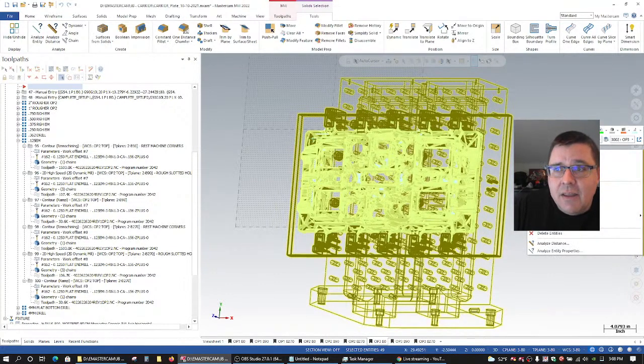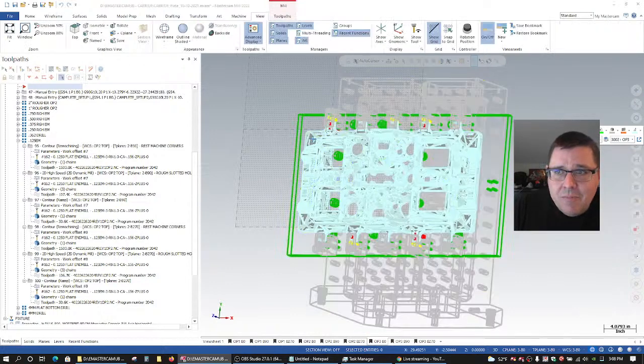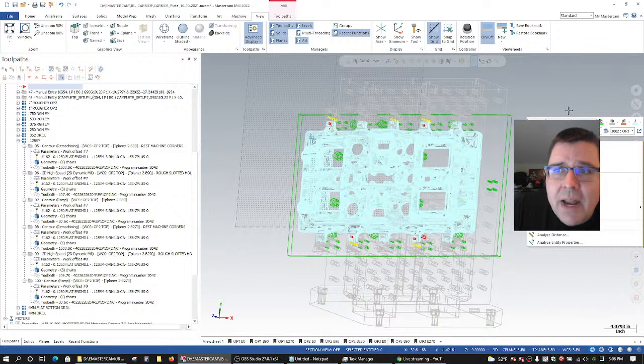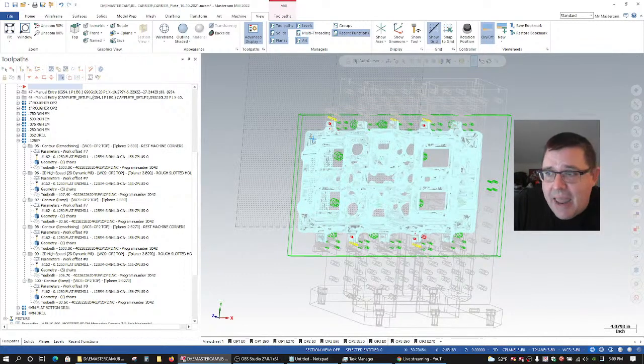I'm going to right click and I'm going to go up to my line width command here, and I'm going to choose the thinnest weight of line, and then I'm going to do the same thing by just right clicking with nothing selected so I can change my current display attributes.